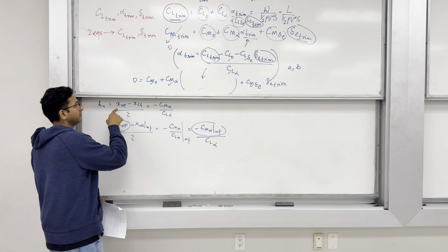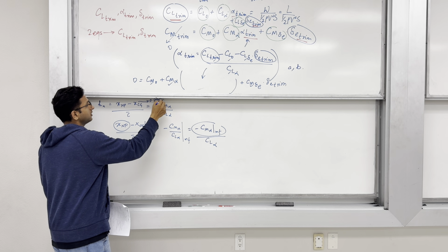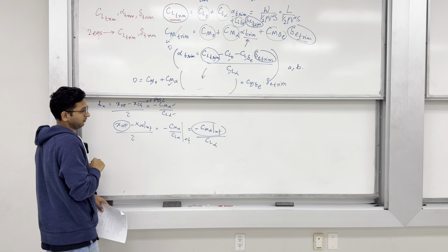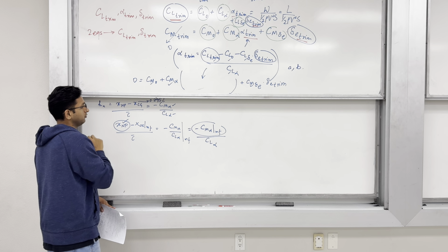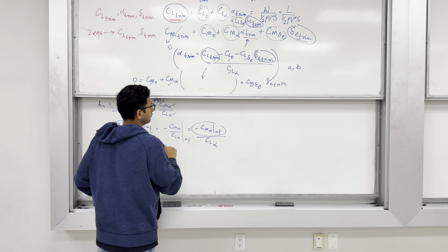X neutral point can be found out from the original data, where you have x CG at 0.295, the earlier configuration, for which CM alpha is given to you and CL alpha is also given to you. So, neutral point's headache is over. What I need to get is negative CM alpha most forward.